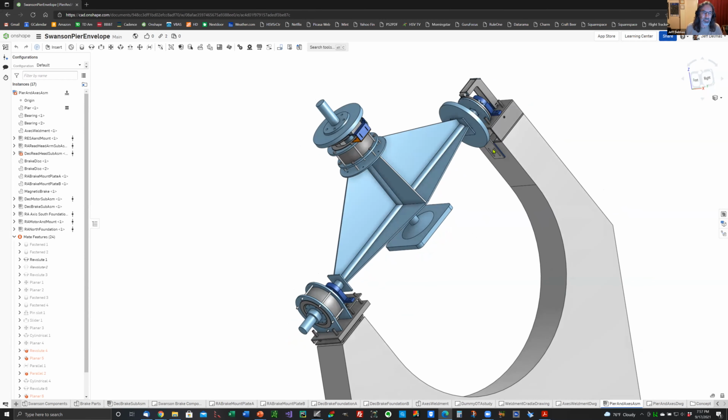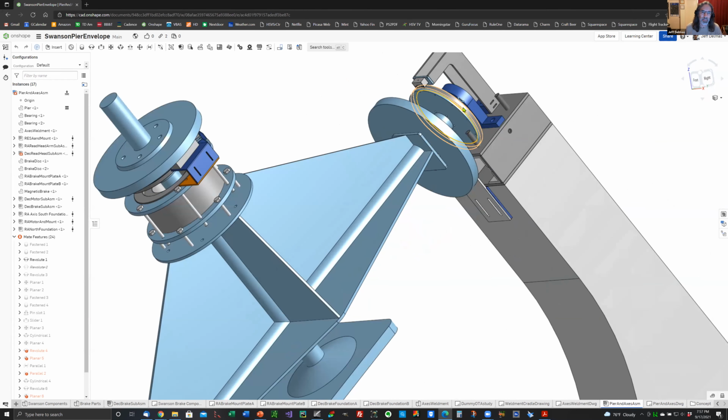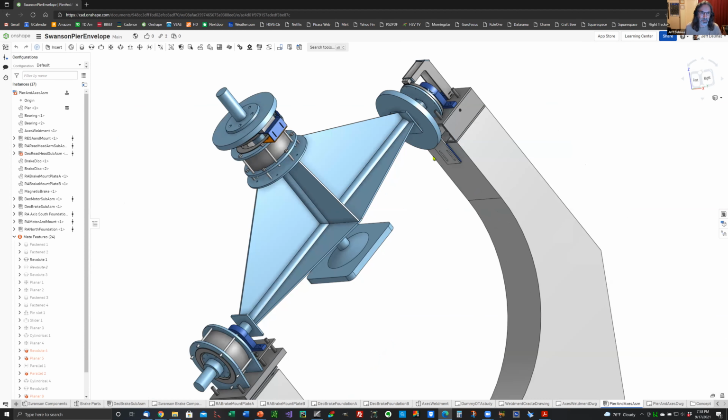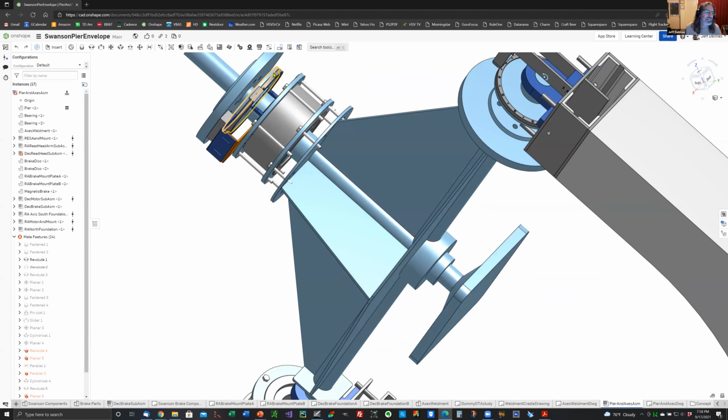And then the other major component that we're adding on are these encoders up here. The encoders are not part of the motor. In the old system, there were encoders built into the motor, and the motor pushed through a clutch system. So if I pushed on the telescope, the motors wouldn't move, but the telescope would move. So the encoders couldn't tell the computer that the telescope had moved. But these encoders, one there, and then, let's see, it's actually in here.